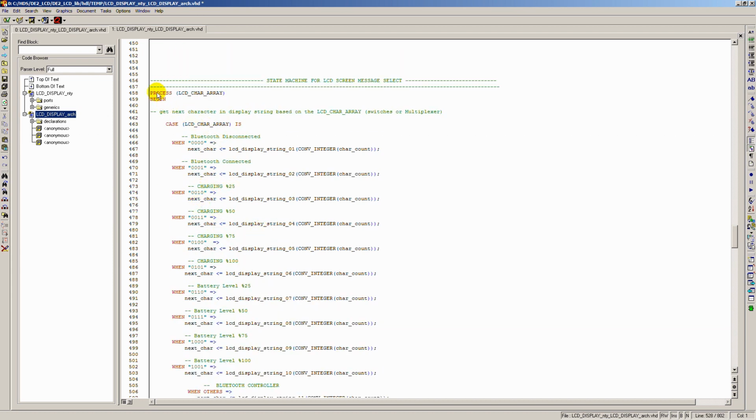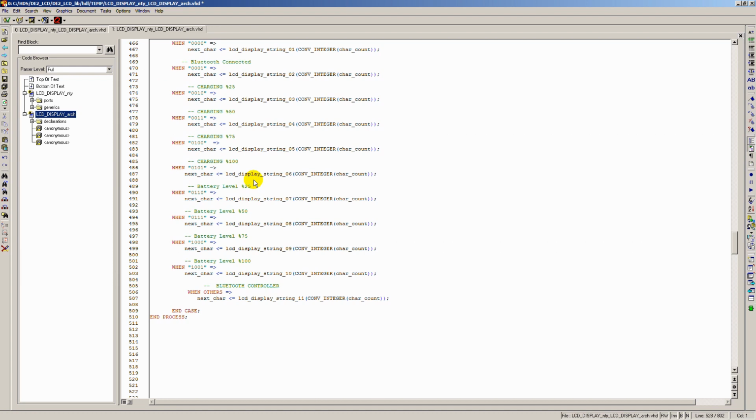But if you have multiple processes, all of the code within each process is being executed simultaneously. So with VHDL you have both sequential and parallel execution of code happening at the same time. That's the real difference and advantage of VHDL and Verilog and the different hardware description languages used with FPGAs and CPLDs and whatnot. So keep that in mind.